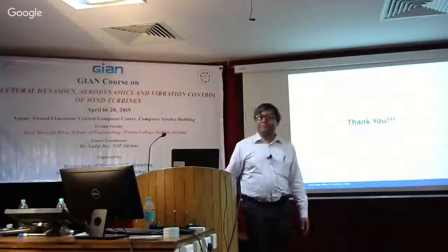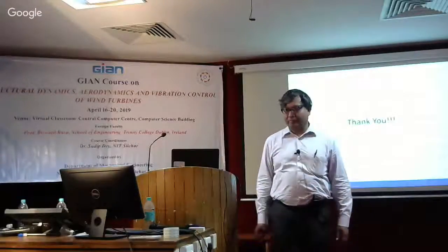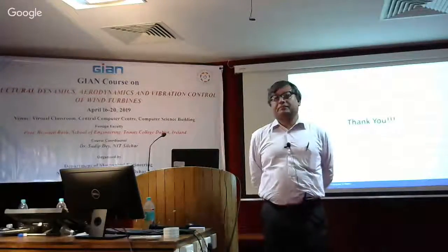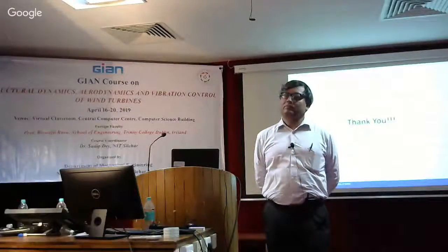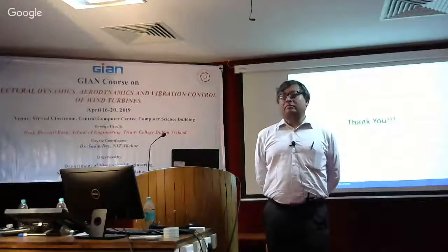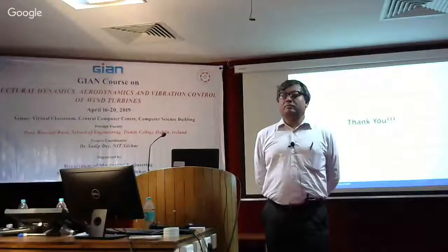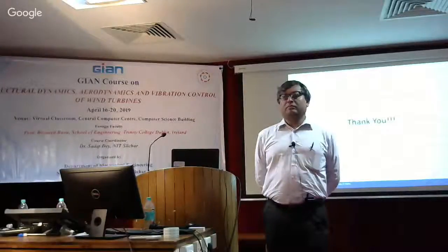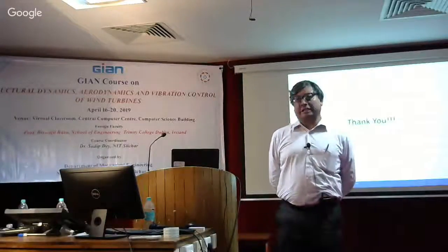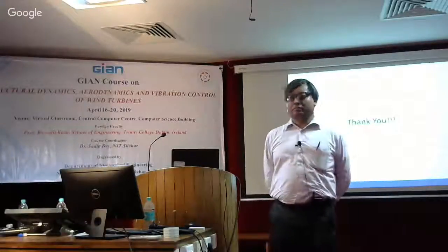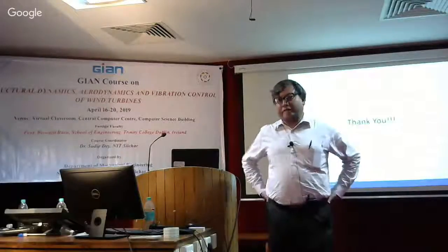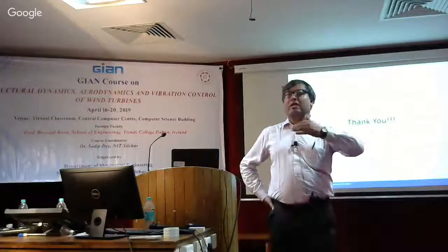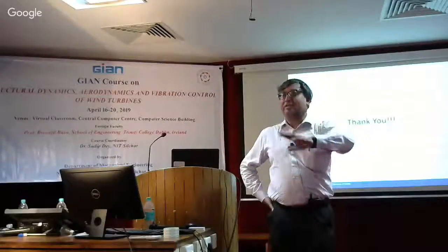So, you have shown that without pitch control, with the active tendon, we can achieve the same. But in the case of pitch control, we are applying it for getting the rated RPM. That's different, so RPM will change, and for that we would have to change the generator, because we are maintaining the rated RPM according to the generator capacity. That's right. So in that case, we have to replace it. Yes, pitch control will have to be used because vibration control has no role in generator control.